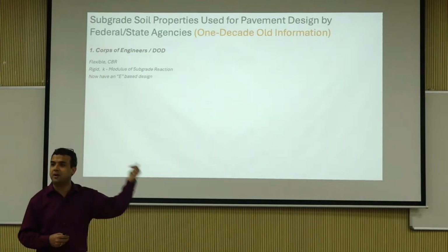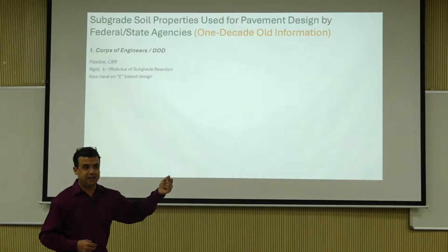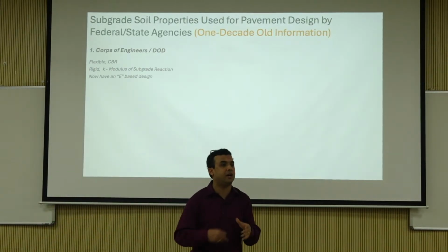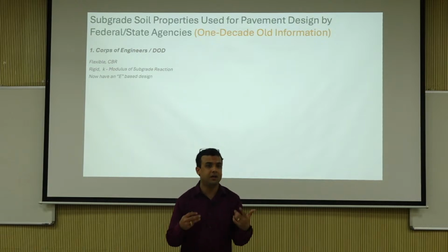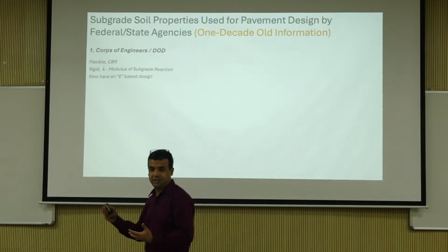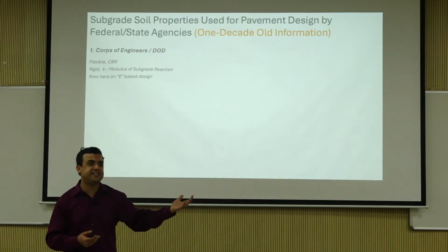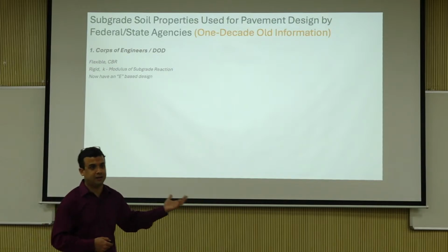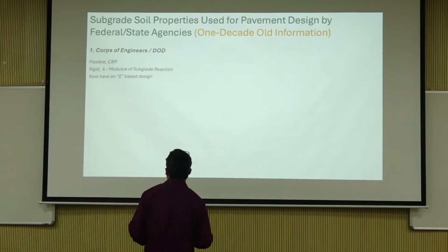They need the information like yesterday, right? So that is the reason a lot of their work has to still be based on empirical or quick tests. They cannot do, you know, even a simple CBR test is a 96-hour soaking, right? It's 4 days. That's a lot of time. You can't afford that, right? So a lot of quick tests and stuff.